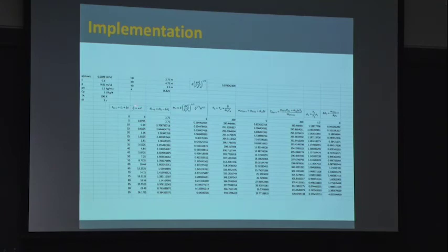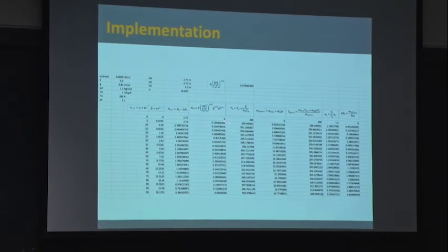Then my next column is my alpha T squared, so I have the heat release rate as it is increasing, okay? And then effectively I can calculate the height. The original height is the height of the compartment, so my initial value is going to be 2.75, which is the height of the room, okay? Then with the height of the room, the heat release rate, and all the constants, I can calculate the entrainment.